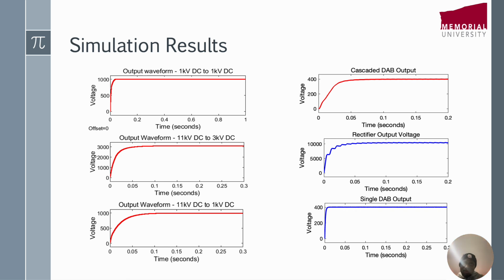And the same way we can also keep the other side at 11 kV, that is the secondary at 11 kV, whilst we connect the primary side in series in order to get our 132 kV. And these are all the results of the various scenarios that we ran.